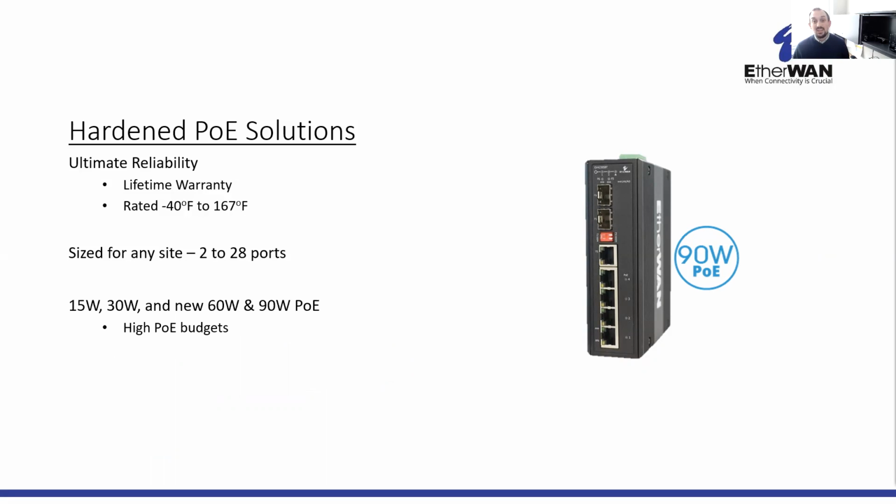So a lot of those guys can get by with switches that have maybe the ability to do 30 watts of PoE on a port, but only a smaller total of power because they're only going to power 1 to 2 devices off of that switch. They don't need to have full power for every port that's going to be on their device. We often do. On our end, it's the opposite. We're really pushing these things, and now beyond 30 watt.